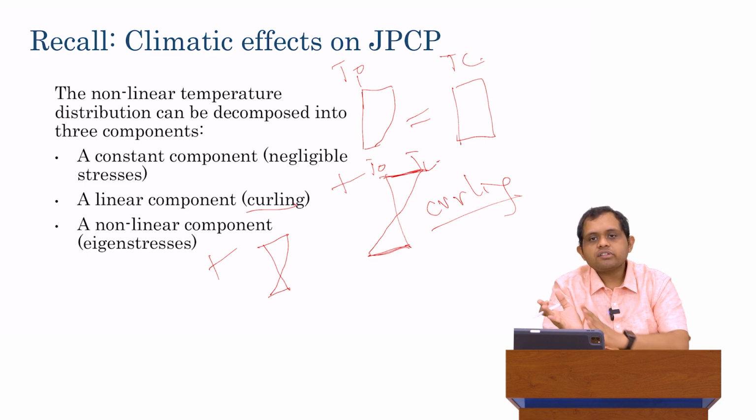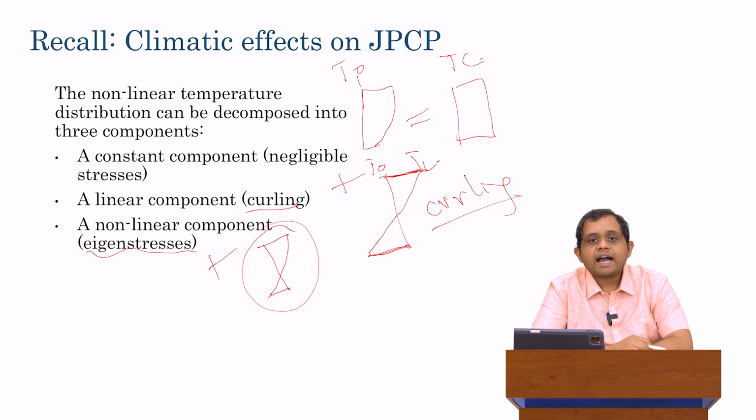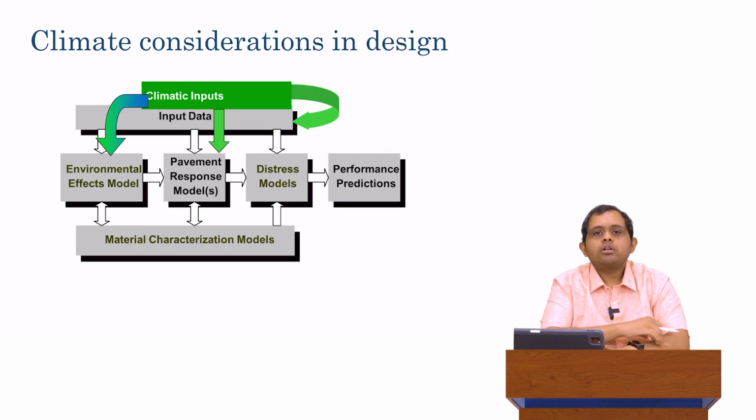In doing that process, an additional stress is developed, which we call an eigenstress. It is created due to this non-linear component. The eigenstress does not depend on any external loading. It is an inherent stress which is present inside the slab. Okay, so we saw all of this.